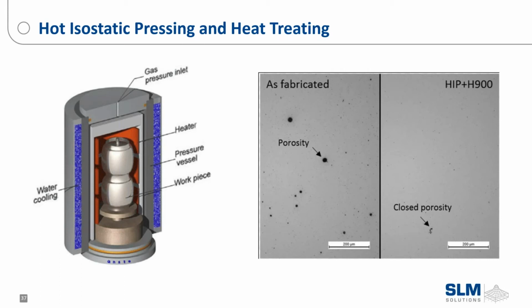That vacuum furnace is pulled down to a complete vacuum, then heated and run. There are specs on most heat treats for most materials already, so this is something we understand very well. We understand how we want the metal to react in the end, and what type of heat treat and post-processing needs to be done from the as-printed material to reach the specs the part requires.